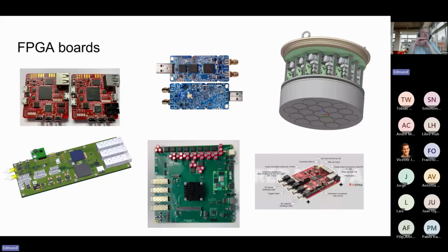Below that, in the lower left corner, is a board for radio astronomy. So there is the data communication link on 10 gigabit, which can be daisy chained, because a lot of those digitizer boards are needed for a radio telescope. And it also comes with a PTP synchronization hardware, so that every board is really synchronized to every other board at the nanosecond level.